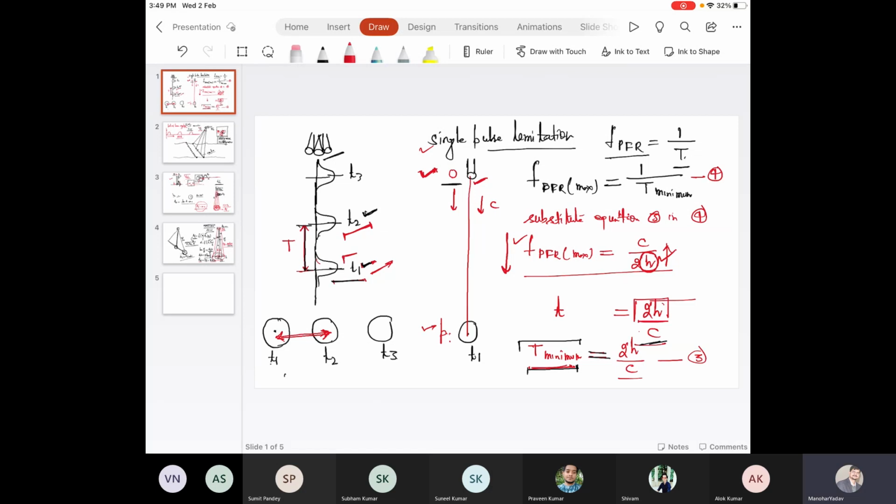That value decreases. And finally, that leads to an increase in gap between two adjacent laser footprints. It means the point density, quality of data will decrease. How this distance increases, we will derive an equation for that later on. But here you can establish a relationship between the quality of data, dependency on pulse firing rate, and dependency on flying height.